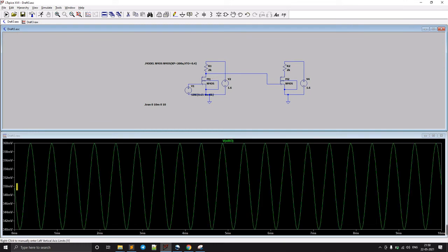This starts from 350 millivolt to 360 millivolt, which is less than the VTO, the threshold voltage for this NMOS. So make sure that here we are getting a voltage greater than 0.4 volt, because we need to maintain even this circuit in the saturation region. Now we are not maintaining this circuit in the saturation region, it is just in the cutoff region because our output is just 350 to 360 millivolt, which is not sufficient because it is less than 0.4 volt.